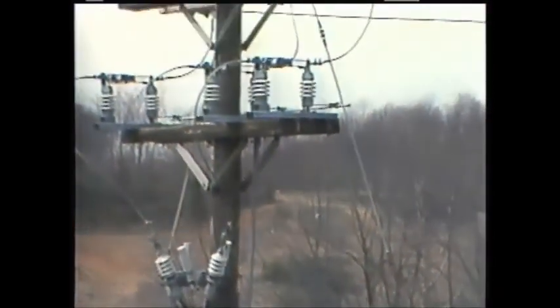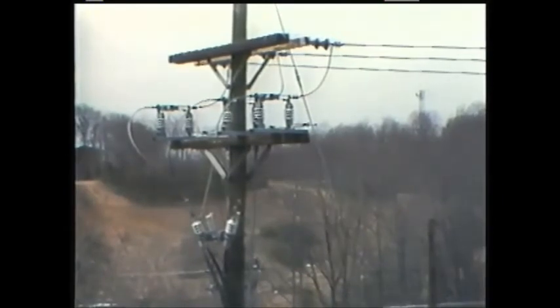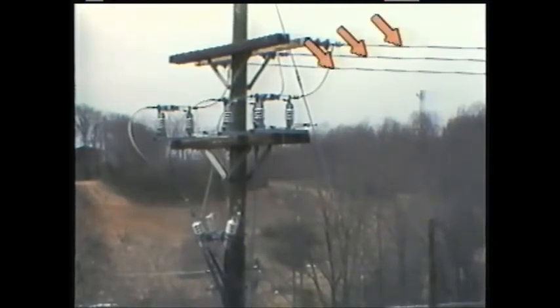A feeder is made up of a number of wires that carry electrical energy at primary distribution voltage from the substation into a service area. In most systems, primary distribution voltage originates as three-phase power. Feeders, sometimes called primary mains or mains, consist of three individual wires that are buried in the ground or strung overhead on utility poles. Each one of these wires carries one phase of a three-phase feeder.